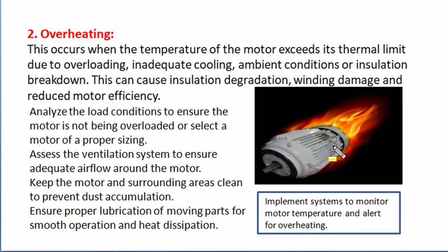Overheating of a working induction motor is the most common failure in a three-phase induction motor, and overheating occurs when the temperature of the motor exceeds its safe thermal limit due to overloading, inadequate cooling, hot ambient conditions, or some breakdown in insulation. Such overheating will cause insulation degradation, winding damage, and it also reduces motor efficiency as increased temperature would have higher winding resistance and copper losses.